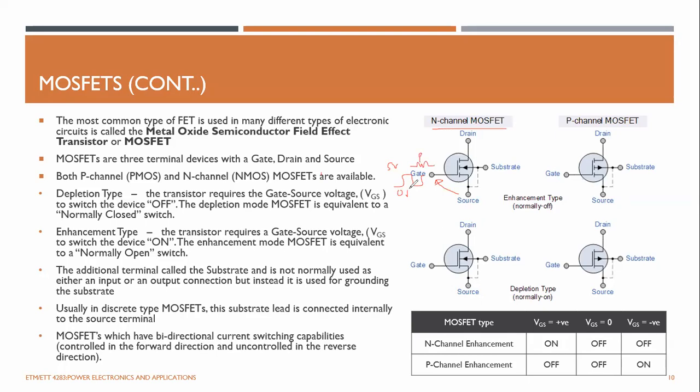So there's no purpose of using a control because you don't need to control any current through this device. It's just voltage driven. Another interesting thing is there are some parasitic capacitances across all three devices. You have to consider that when you're dealing with high frequency drivers.